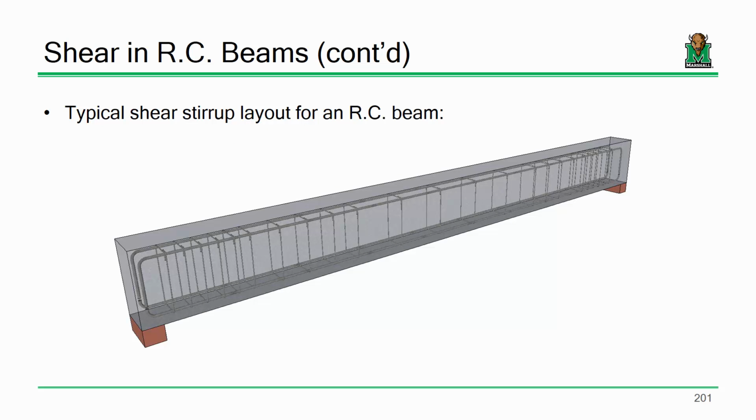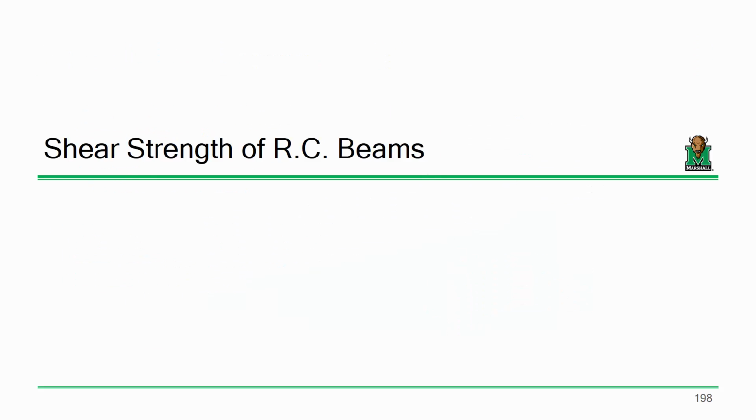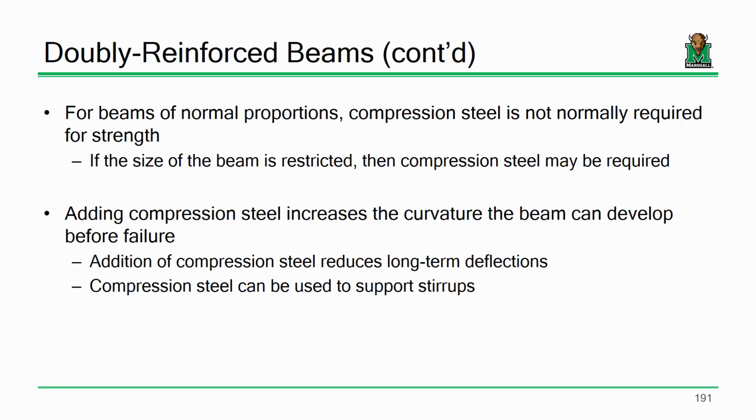What I mean by doubly reinforced beams is something like this, and this is just a rough conceptual drawing to give you an idea, but if you look at the rebar inside of a reinforced concrete beam, we tend to call it a rebar cage. Usually you have a bunch of steel at the bottom. That's your tensile reinforcement. These stirrups, these bent pieces of rebar going like this, we're going to look at designing those later. That's to resist shear. But to tie everything together, you tend to put a couple bars on top anyways to make the cage sort of solid and whole and what have you. So that's what we're going to look at: what is the contribution of that reinforcement.